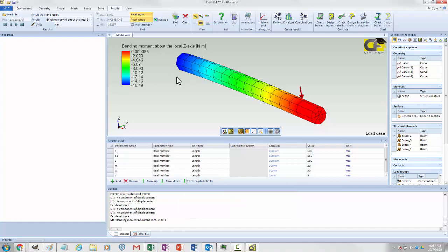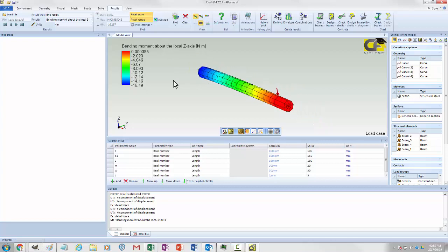For our more complex and available beam sections, this is not required because then the values of stress are automatically calculated for us. But because this generic section doesn't have any dimensions, the software wouldn't know what stress to produce in this case. All right, so that was the procedure to generate results using a beam element. In the next video, we are now going to create a shell element that represents the exact same section.